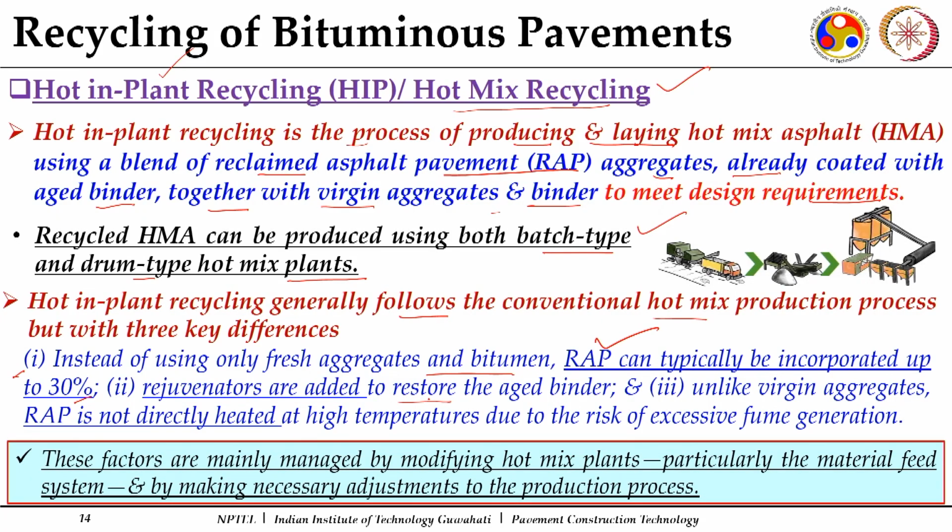Rejuvenators are added. This is another important feature during the production of the recycled mixes by these batch type or drum type plants, that rejuvenators are added, because the binder which is present in the RAP is a highly aged binder, so it needs to be rejuvenated. So for that, different kinds of rejuvenators are popular to restore the aged binder.